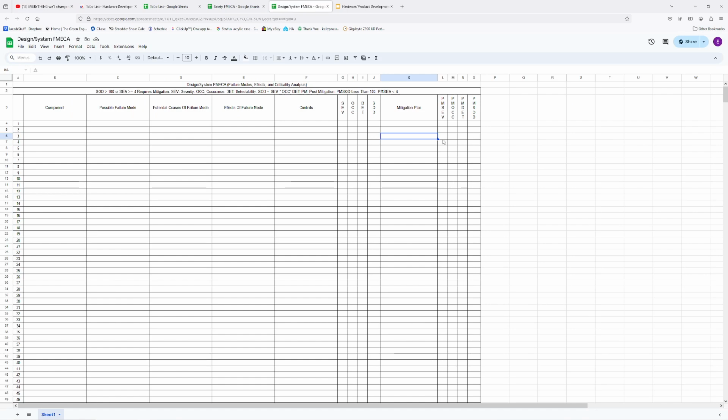Make it a stronger plastic, injection molded, more repeatable. Maybe you have fewer voids in your print, so it's repeatable because it's injection molded. You have some sort of FEA, FAI, first article inspection, or quality inspection, right? And then before you ship it, check for delaminations, check for cracks, do some sort of dye check for a crack, like Dykem or something. Check for cracks, delaminations.